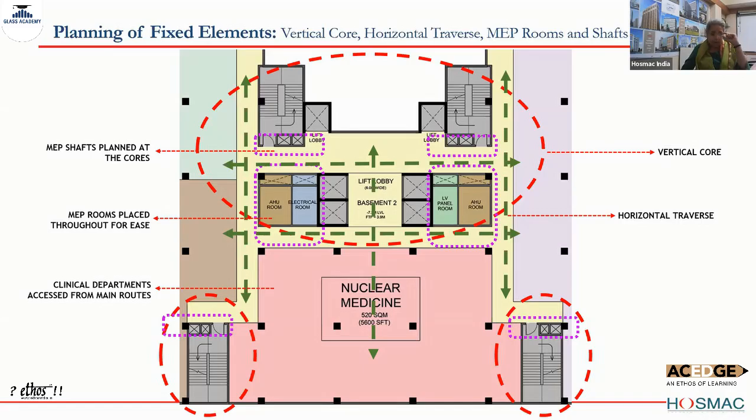Now the new bylaw which has come into Mumbai, this is for the rest of India, the whole of India. The new bylaw which is working in Mumbai is that between two staircases, a meandering walking distance through corridors can be 60 meters in a building with sprinklers for healthcare. So we have just done a project which is very tall, a 75 meters height project, where we have gone for this by rule. Now, this again is state to state. 45 meters between two staircases, the safest, please go with that.